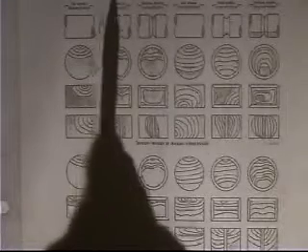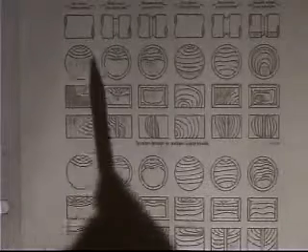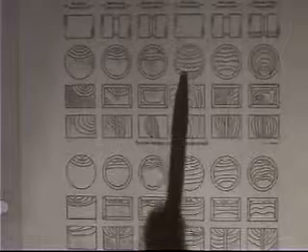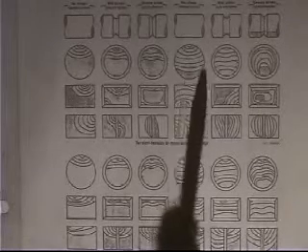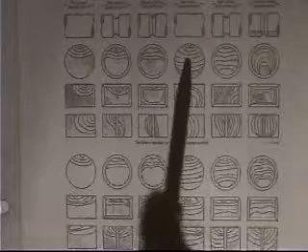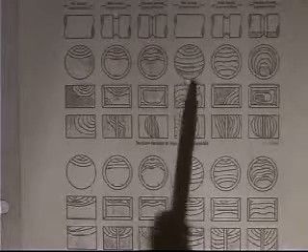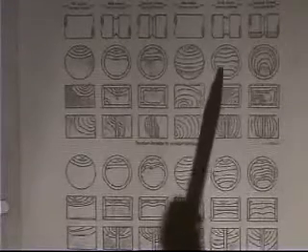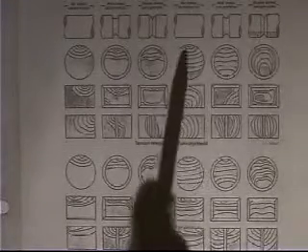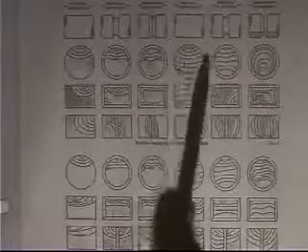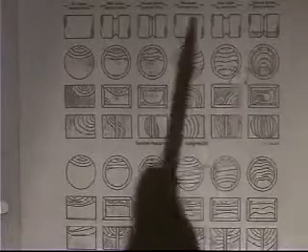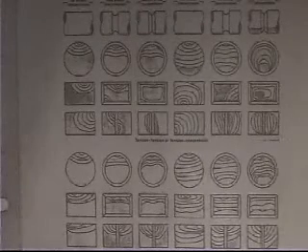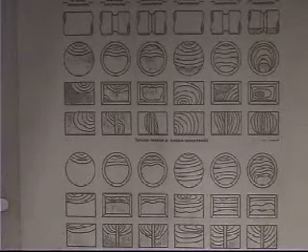If it's high average stress, the part has a high stress on it, you'll see a large area. If it's a low nominal stress, you'll see a small area, and the fatigue crack will cover most of the area. Now, if you have something like this, where the fatigue crack, well, actually, let's go all the way over here. Let me back up. There's all kinds of bending of these lines, and that has to do with whether you have a stress concentration, whether you have a notch that magnifies the stress or not.